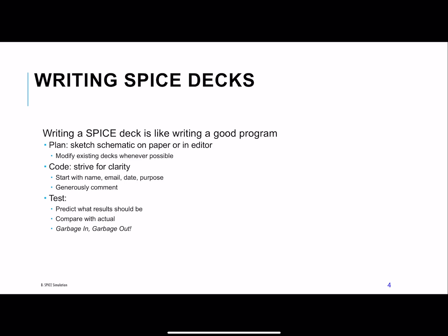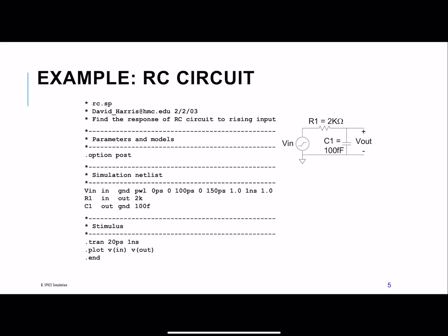I usually throw in an inverter to start with, just to see if the model files make sense. I might do an IV curve of the NMOS and PMOS. Just like with a regular computer program, take it step by step rather than jumping all the way in, where you might run into trouble and not even know it, or it'll be hard to debug.